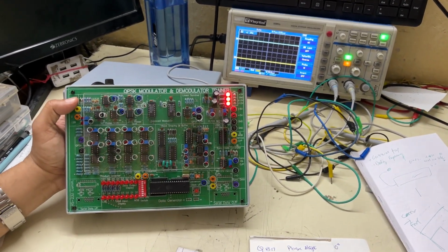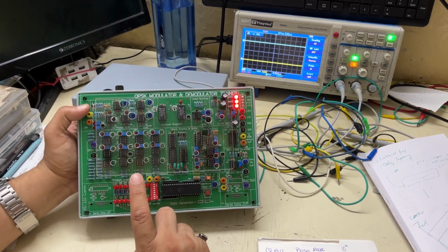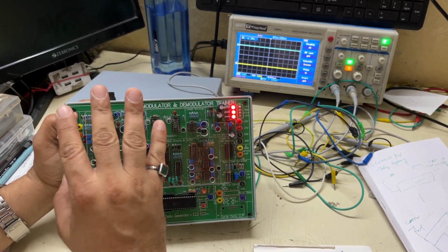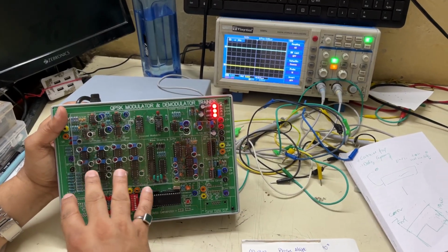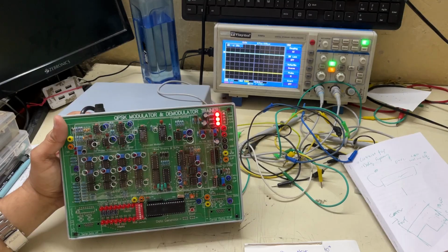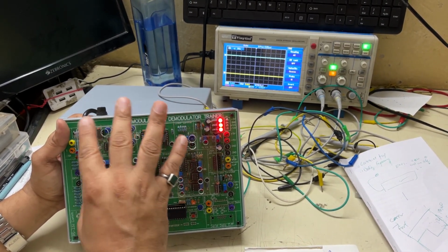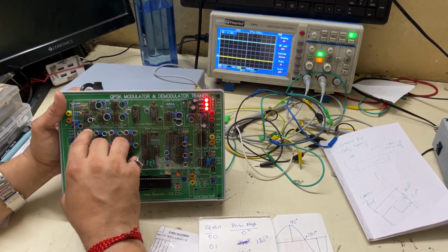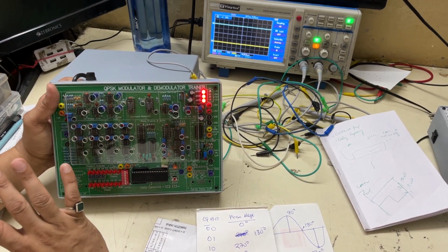The actual thing happening is that our digital data signal is converted in modulation using the phase shift as a modulation technique. For the actual process, which is also used in every modem outside right now, we are using a reference carrier, which will be a sine wave, used as a reference point for considering the phase shift. Next are the 90 degree phase shift, 270 and 180 degree phase shift.